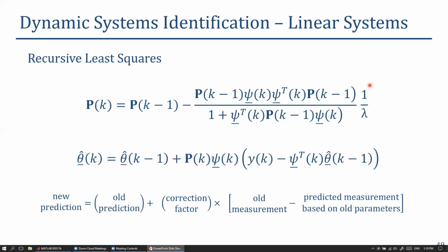And now this is important if our system changes fast, changes quickly. So imagine that the mass of the vehicle changes relatively quickly. That means if you want to update and get the correct model parameters, then lambda should be smaller, lower. And if it doesn't, then lambda should be bigger. So the choice of the forgetting factor depends on how fast our updates need to be done, right? And this is the designer parameter. That means it's up to you to select it correctly.